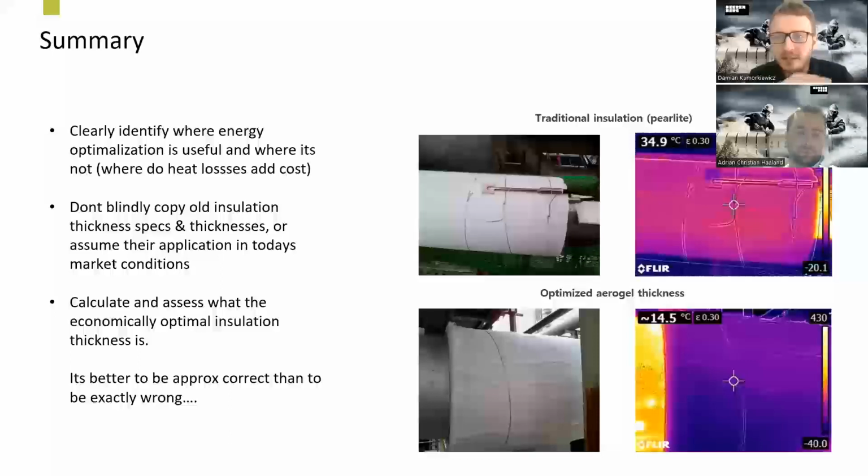In the material list, mineral wool is missing. Why? Because in a lot of chemical processing plants in South Korea, they're not using mineral wool very much. They're using perlite, which is the Asian equivalent. It looks and feels almost like a gypsum board. It's like a rigid shell. It works kind of the same way as cellular glass, but it's different.